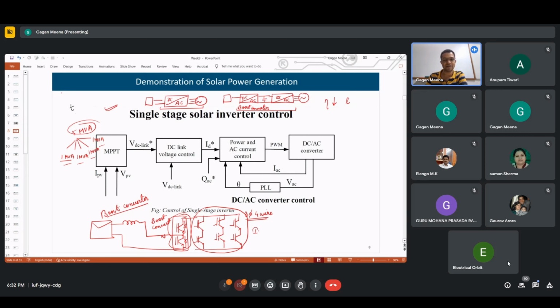So we don't have the actual battery. We are modeling them inside the Opal RT. And whatever control logic we have developed, we are also burning inside a DSP based processor. Then we are checking whether our algorithm is working fine or not. If it is working fine on this modeled system, because this modeling is as per the actual battery, the actual battery model is also similar to this model. So if it is working fine here, it will work for the actual battery also. Is this clear?